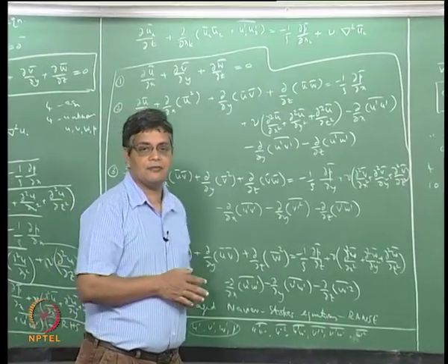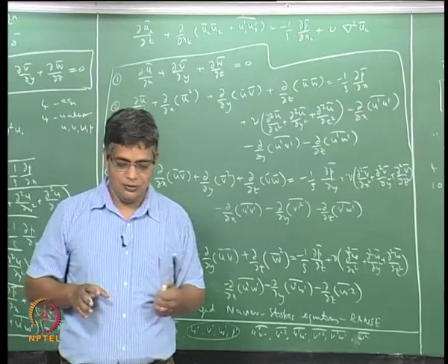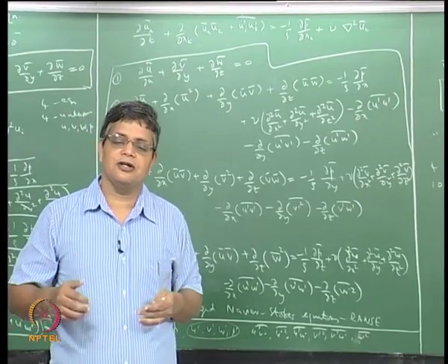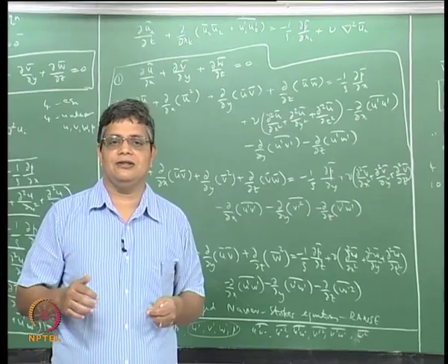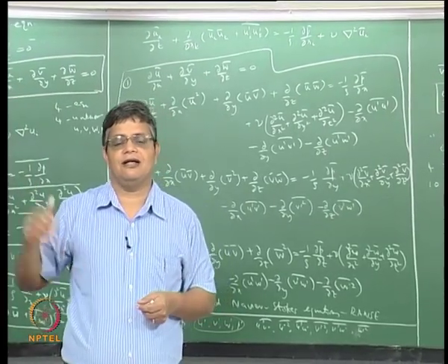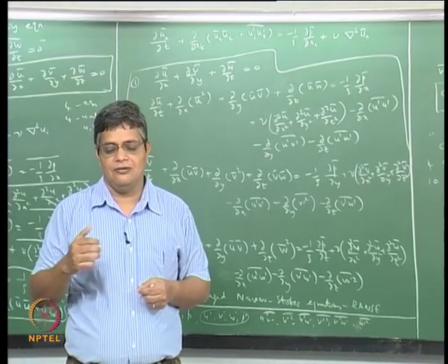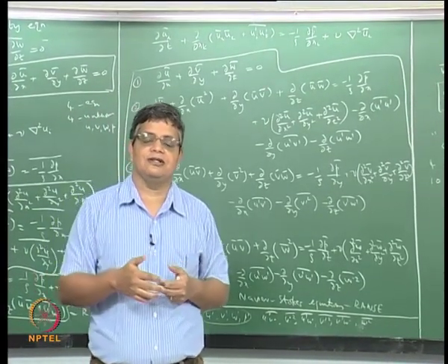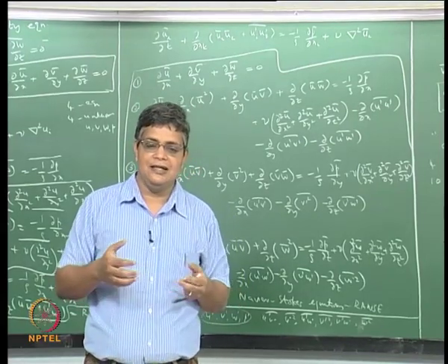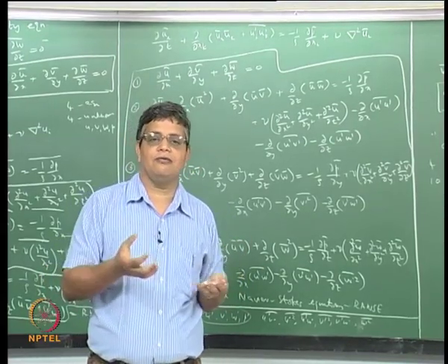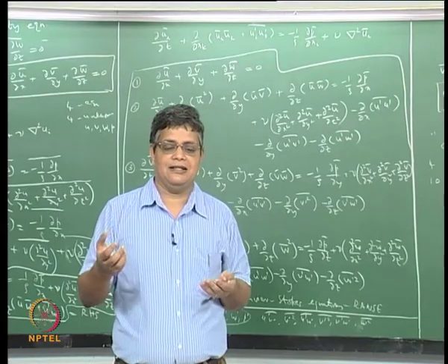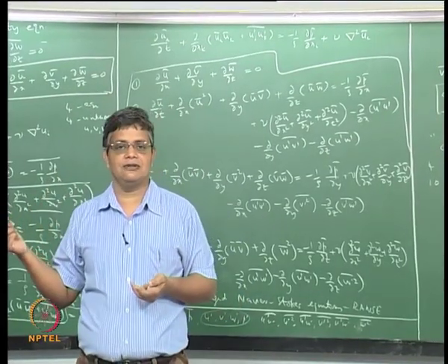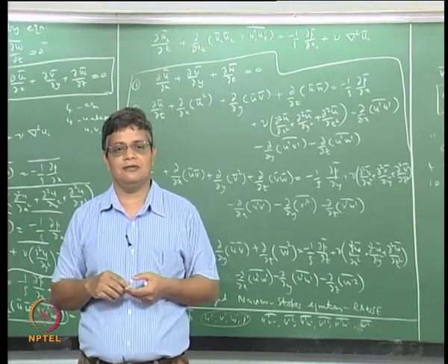In other words, we cannot overcome the problem of closure in turbulent flow if we resort only to the fundamental Navier Stokes equations. So we have to bring in some empiricism, the kind of empiricism that we brought in by assuming a Newtonian fluid and isotropic medium in order to derive the Navier Stokes equations from the momentum conservation equations.